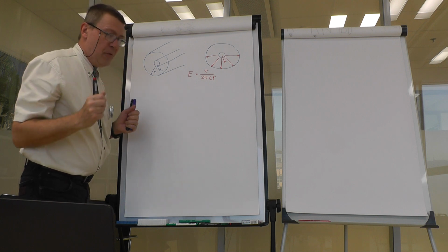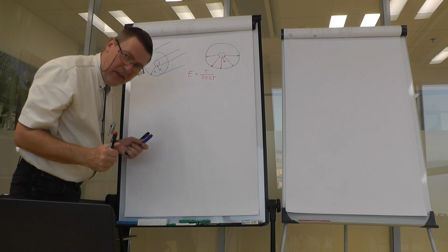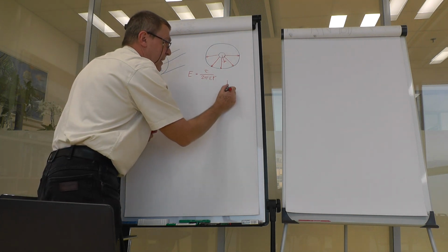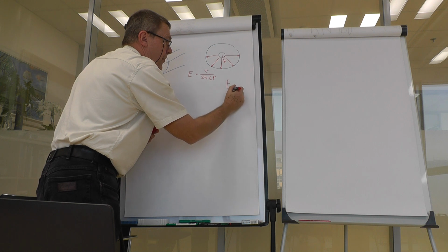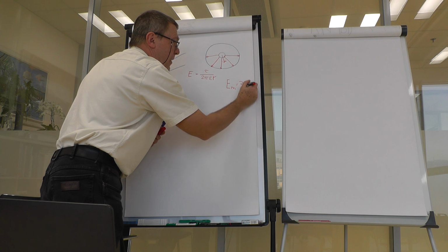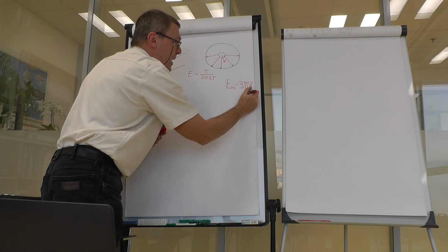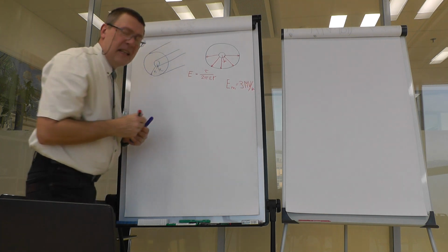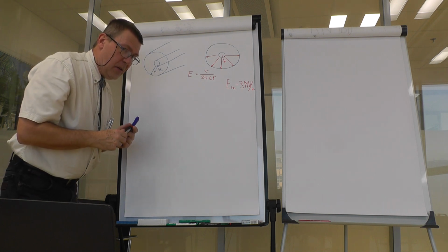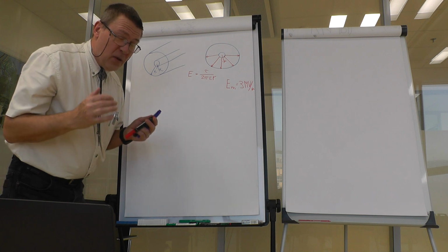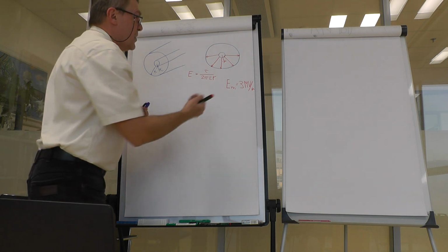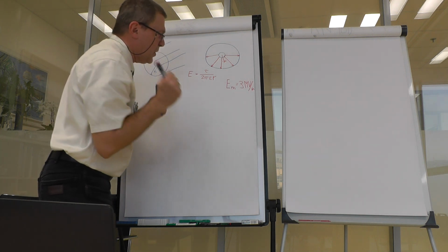Now if we have there air, the maximum field strength that the air withstands would be 3 megavolts per meter. And this holds only for air in good condition. I mean, there is no water in it. So this is the maximum field strength that could be put there.